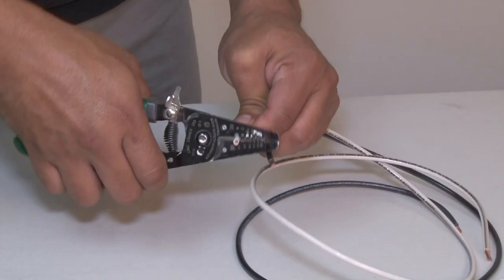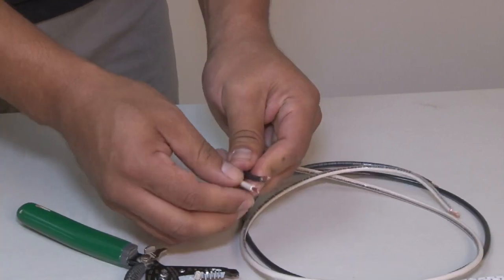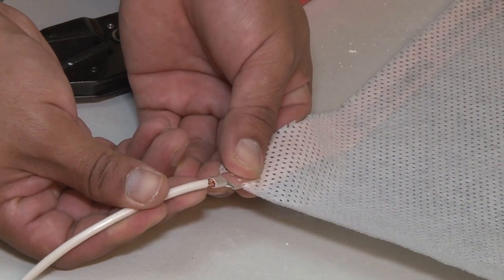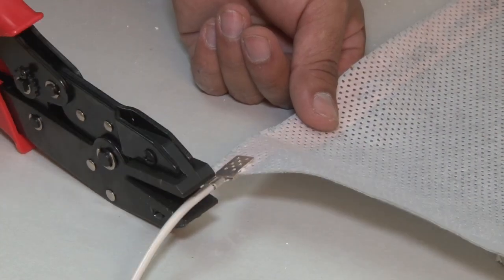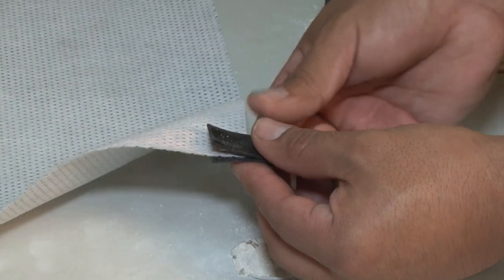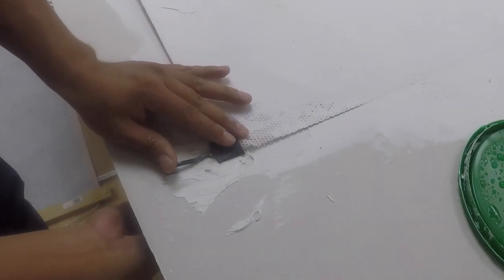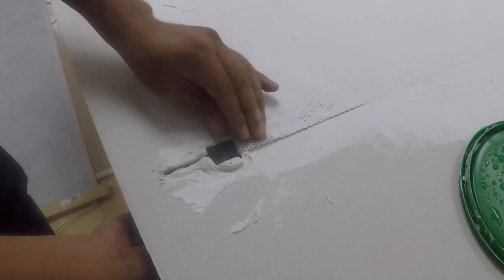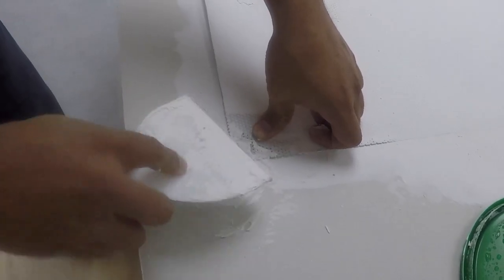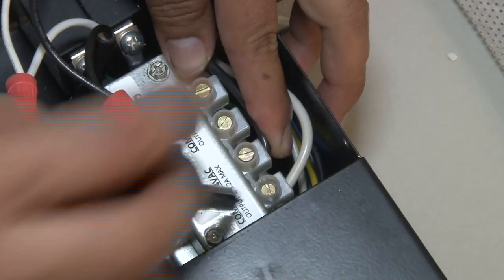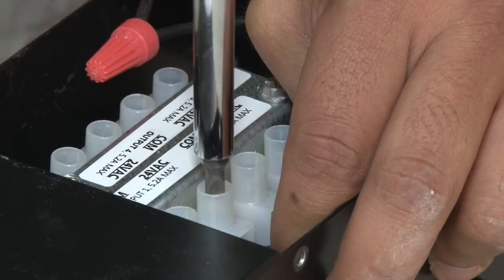Strip insulation off the ends of the 10-gauge wiring, approximately 6.35 millimeters. Crimp 10-gauge wiring onto splice connector that is already crimped onto copper conducting strip on heater film. Wrap splice connector completely with electrical tape. Gently press heater crimped connectors, wiring, and tape into the bed of plaster and apply top layer of plaster to cover. Route heater cables from heater film segments to the load terminals on the installed terminal block in the transformer.